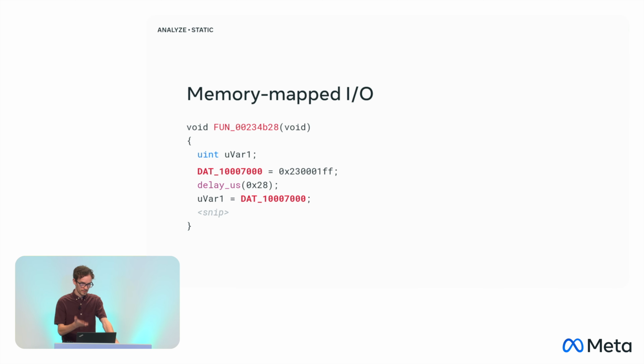And so this brings us to what's called memory mapped I/O. This is a fixture of basically any modern chip, from the tiniest little microcontroller up to a full desktop CPU. And the kernel, or whatever's running directly on the hardware, will be using this to perform actions. So here's a real function I found while reversing a piece of firmware. And if you expect all of the memory to be RAM, this is nonsensical, because what it's doing, on the second line here, is writing some static value, saving some static value to this address in memory.